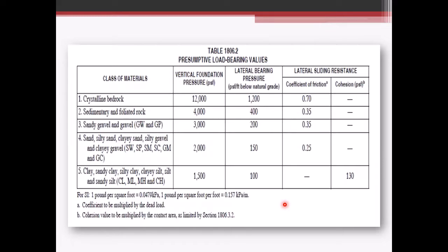The one thing with these tables is they don't take into account the density of the soil. And a lot of times some of these tables may be conservative, so it's always important to make sure that there is some additional lab testing done, or additional field testing, I should say, to verify the density of the material.